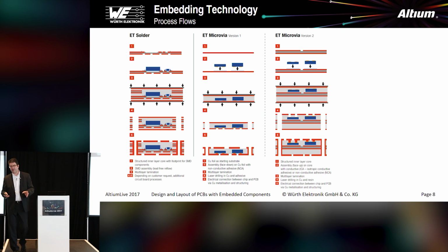So we have no solder inside, no bumps, no gold bumps or whatever inside, which makes it really highly reliable in that area because you have fewer interfaces. You have a direct copper connection. Copper is actually much less brittle than solder, so this is an increase in reliability. But as I said, you need to have components compatible with that one.